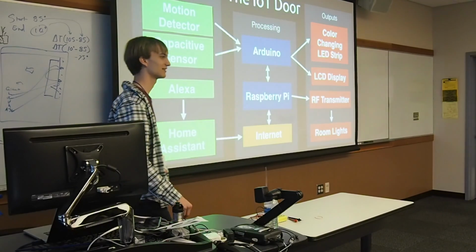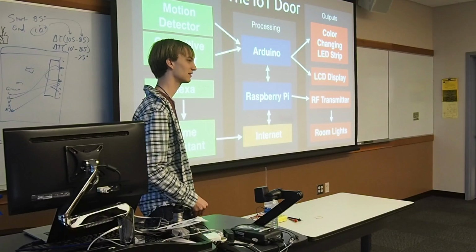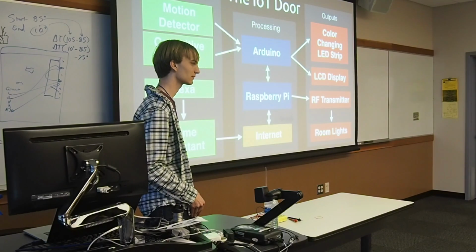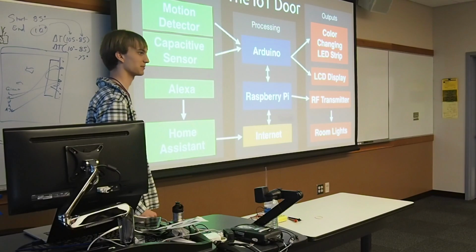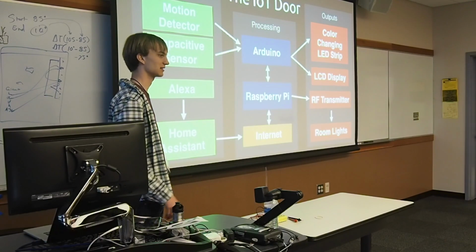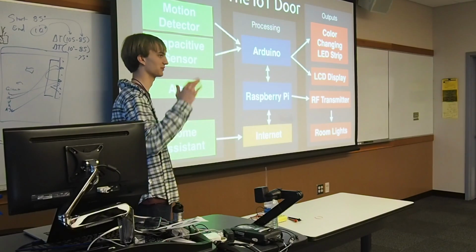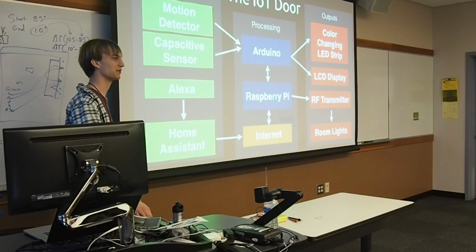So I guess the Raspberry Pi is running a timeshare operating system, but Arduino is just dedicated. The Arduino has hardware for creating PWM signals. The Raspberry Pi is just bit banging it, in software, saying on off really quickly. And that's not quite as fast as the hardware-based PWM.